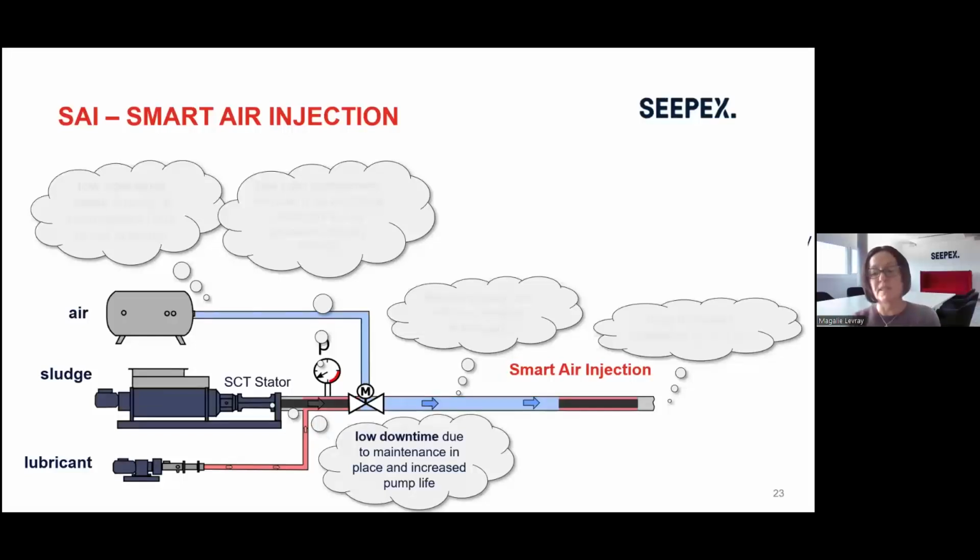We've seen that with SCT technology, whenever the flow rate decreases, the first maintenance operation is actually to retighten the stator, which we can do a first time, a second time before we really have to change the stator. So because we have low pressure feature, we can use SCT and benefit from all the advantages of SCT technology in an application that normally requires high pressure pumps and involves the cost of high pressure condition.